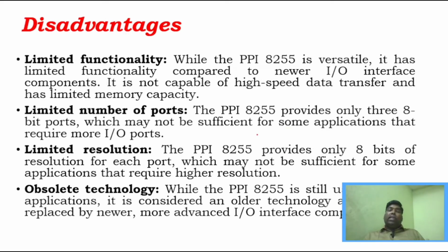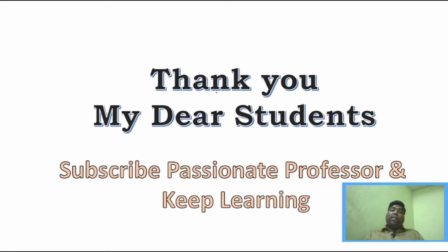When it comes to disadvantages, there is limited functionality because of the 8-bit ports. It is versatile, but the functionality is a little bit limited. Since it is 8-bit, high speed data transfer is not possible. Similarly, it has only 3 ports of 8 bits, so it is limited, and the resolution is also limited. It is an obsolete technology. Even though we are still using the 8255, newer advanced interface components have evolved. So this is about the 8255 operation modes.